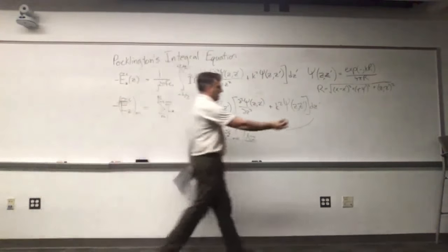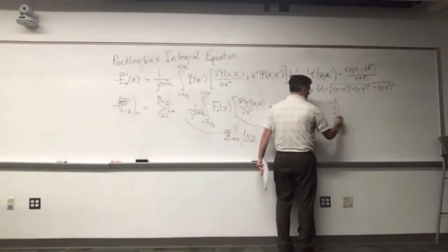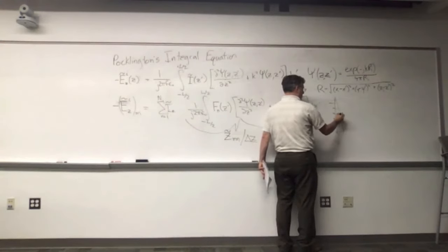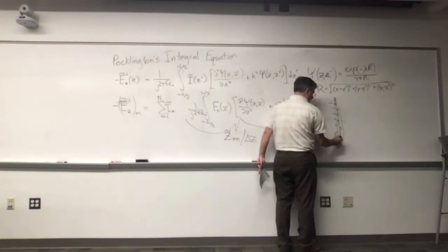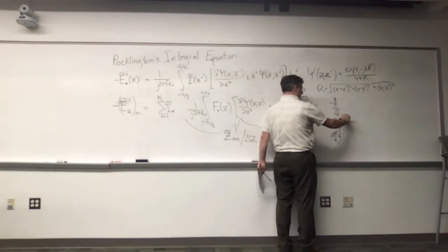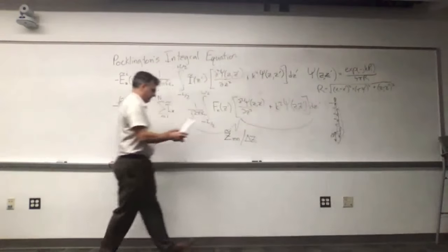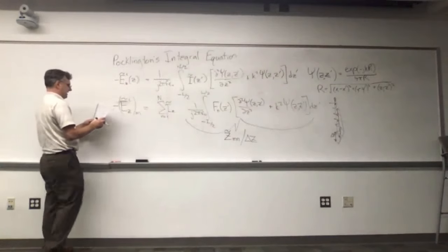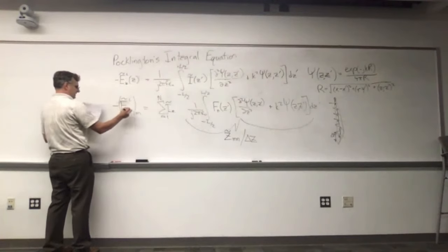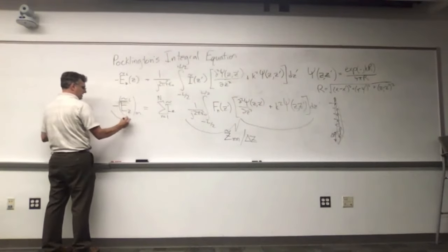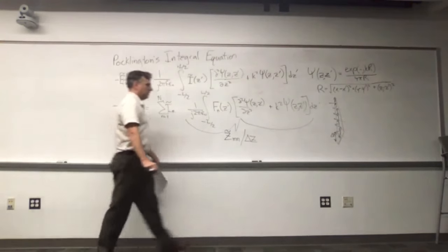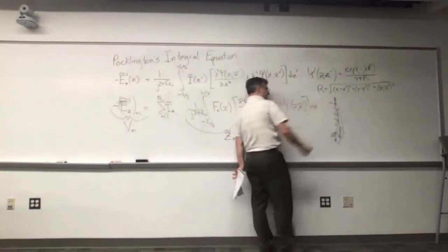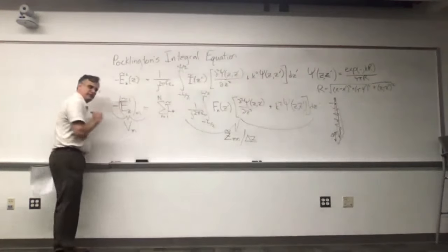Does that make sense? We have a long wire. We're breaking it up into samples. We sampled the current, one here. We're going to have to sample the field too, making it correspond to these delta Z segments at the field moments. In fact, what we would like to write this as is minus EZ. I'm going to write this as the mth voltage sample, the voltage drop across that delta Z element in the mth sample space.